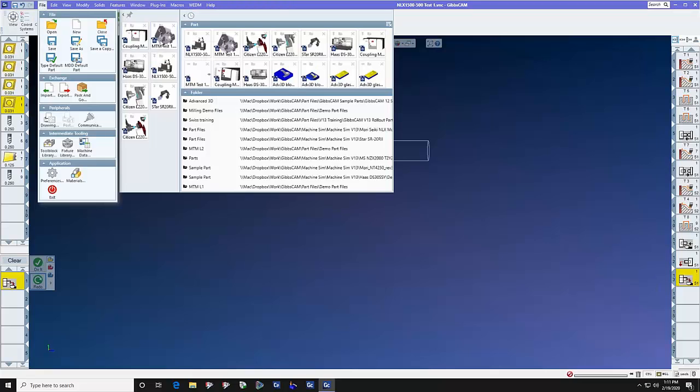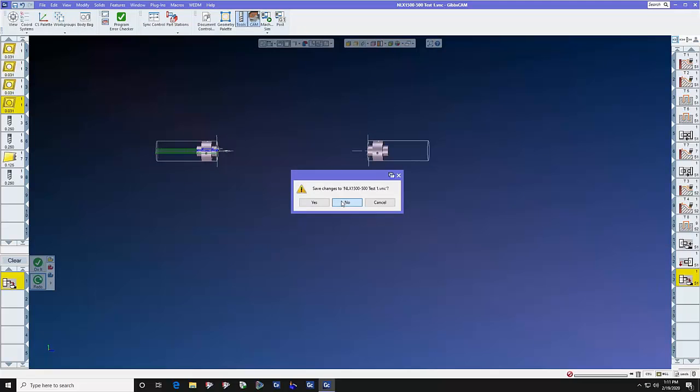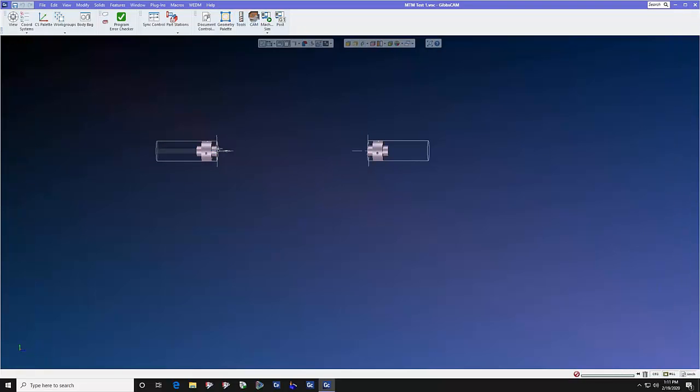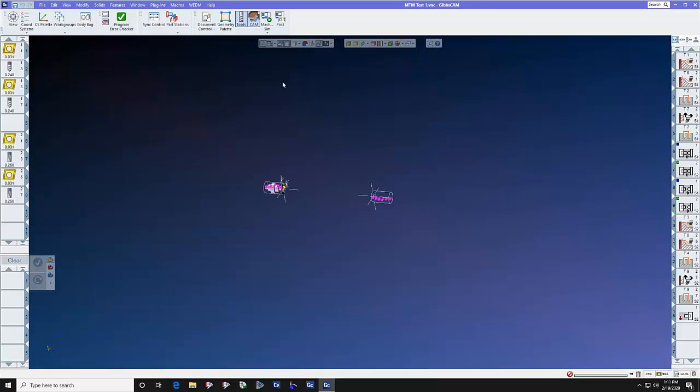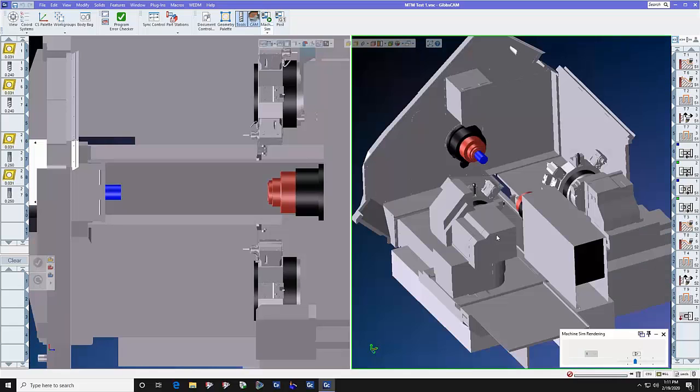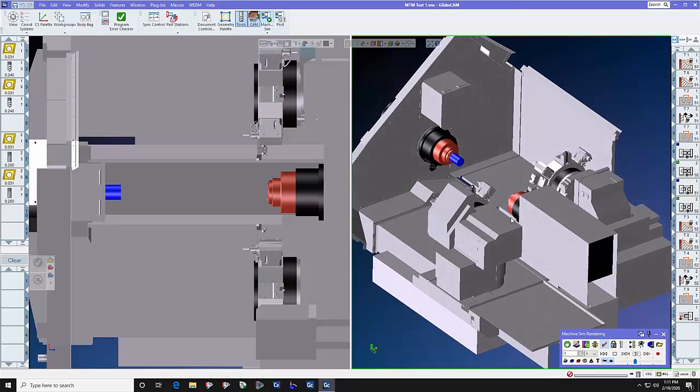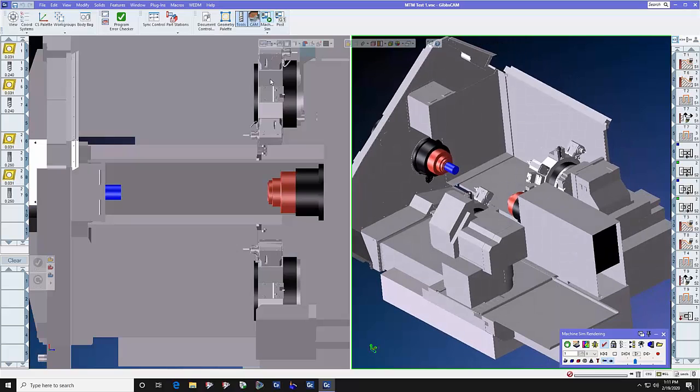We're going to step to a dual flow machine, and we're going to talk about now the machine definition dialog and what a dual flow machine is. This is a two-flow machine or a dual flow machine. It's a Mori Seiki NZX 2000. It has two turrets and two spindles. And we can control all of the synchronizations between the upper and the lower turrets to make sure they don't crash into each other. But let's have a look at the machine definition dialog.